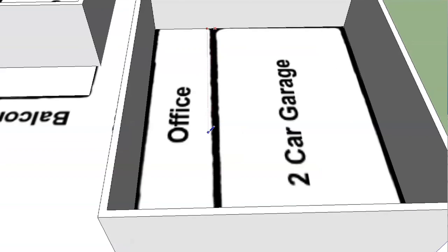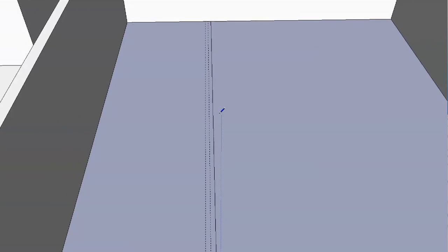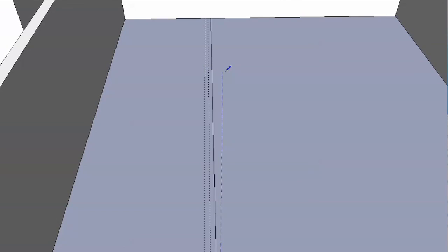Now we can take the line tool and snap. You can see that if we hover, we get those little X's right there, there, and there. Let's find the X on the far right and take a line segment all the way across here. Good. And you can see the instant we did that, we redrew the line, which meant SketchUp recalculated where all of its faces were, so it redrew the floor for us. But you can see now that we've got that kind of purple background, we can see where our guidelines are.